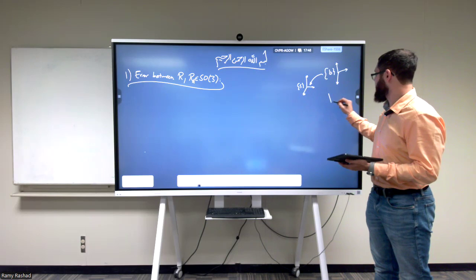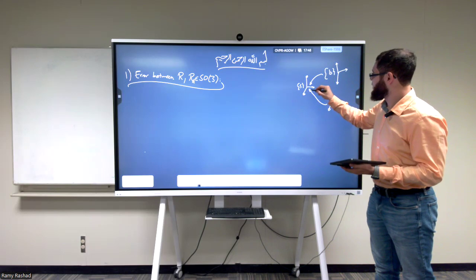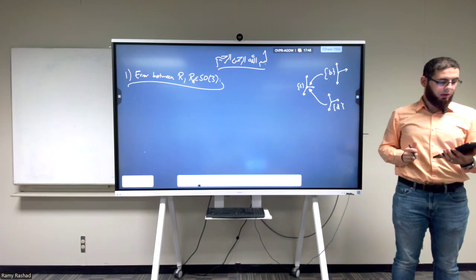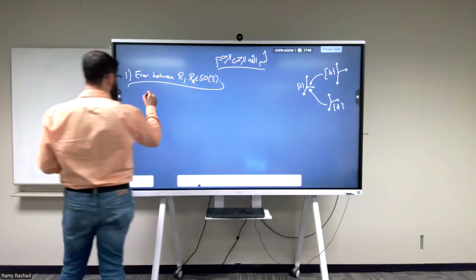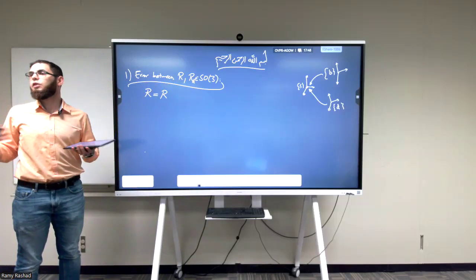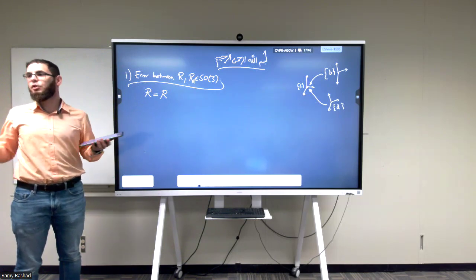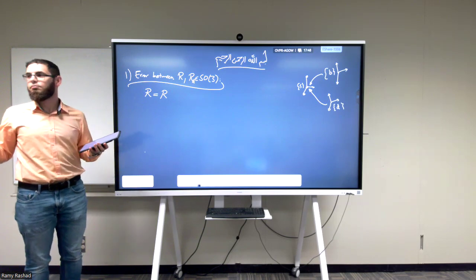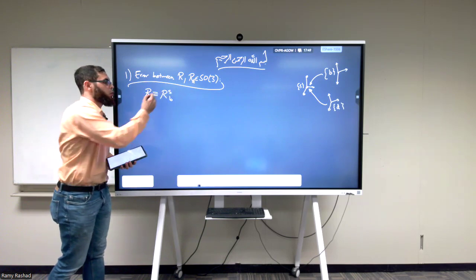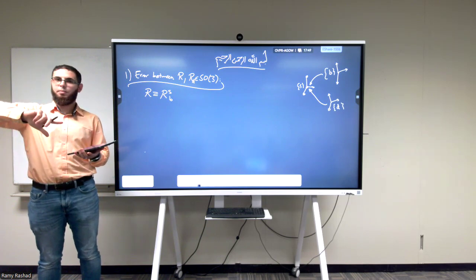We also have another desired frame. And again, all of them are coincident at the same point. They're just rotating with respect to each other. When we say R, we're implicitly meaning which one of these? Which relative orientation? When we say R, the R of the satellite? There's no such thing as RB. There is always RB with respect to S. So whenever we say R, we're actually meaning the relative orientation between the frame B and the frame S.